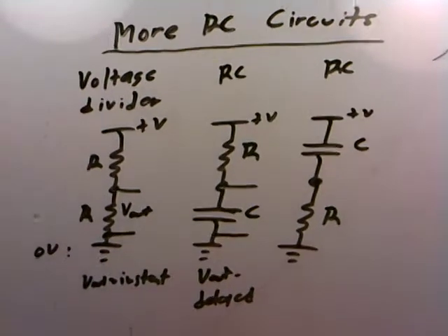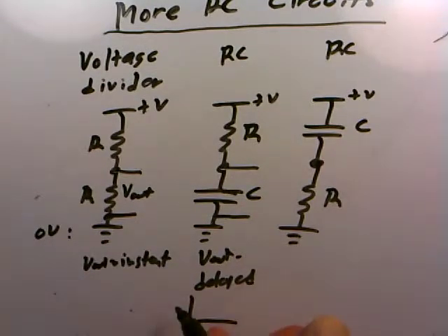In fact, if we plotted the V out as a function of time, so if this is your V here and this is time here, it started at 0 and it gradually rose up like that. It's not a straight line. It's that rising exponential, which is classic for the charge or voltage when a capacitor starts to charge up like that. So we just saw the voltage come up slowly.